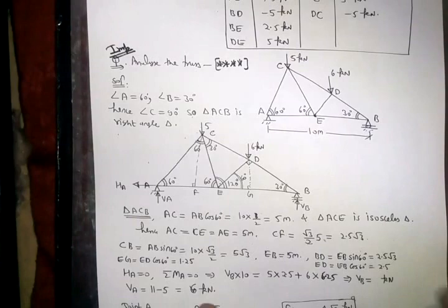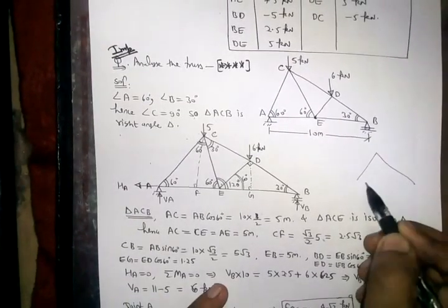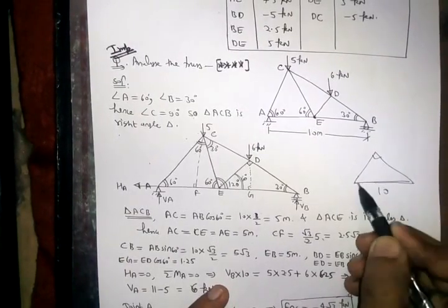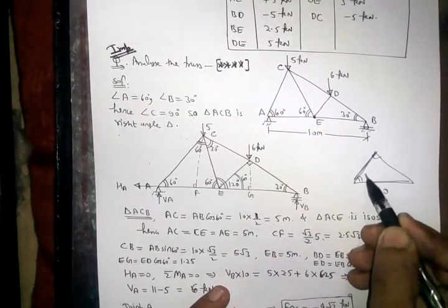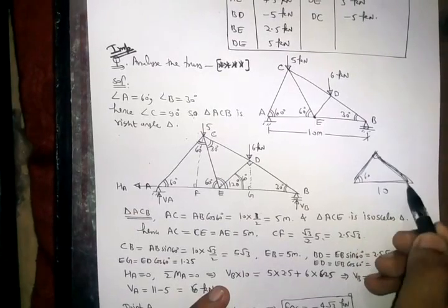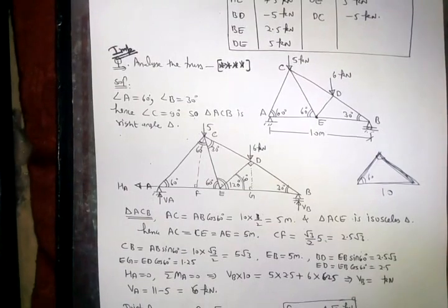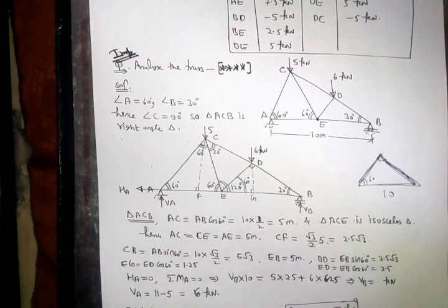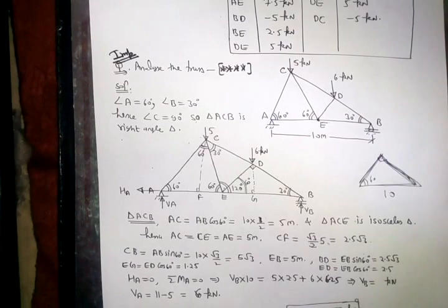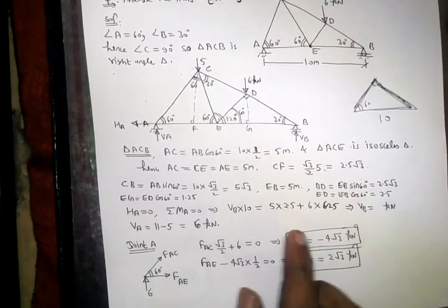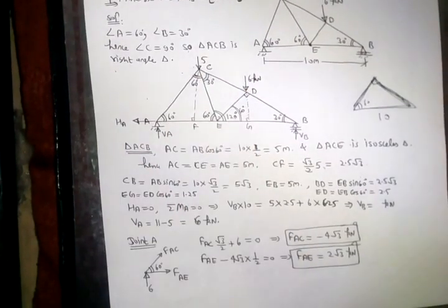This is 90 degrees, na. This is 90, it is 10. So this will be 10 cos 60, this is 60, and this will be 10 sin 60, right? 10 cos 60 and 10 sin 60. So while calculating the angles, we can further proceed. I have calculated all the distances which I required, meaning FC, DG, right? I have calculated these, and the reactions.